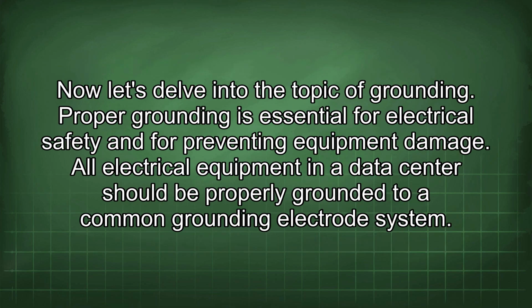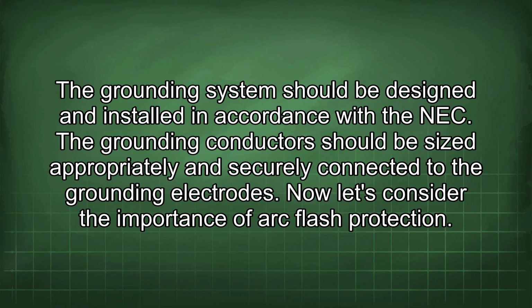Now let's delve into the topic of grounding. Proper grounding is essential for electrical safety and for preventing equipment damage. All electrical equipment in a data center should be properly grounded to a common grounding electrode system. The grounding system should be designed and installed in accordance with the NEC.